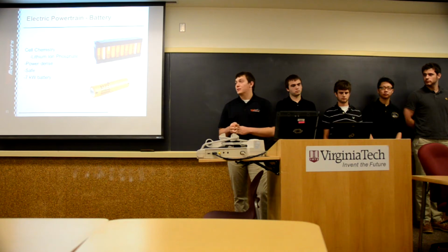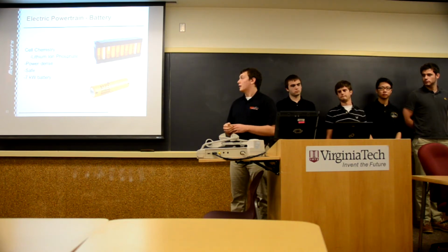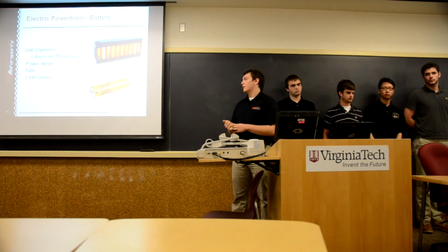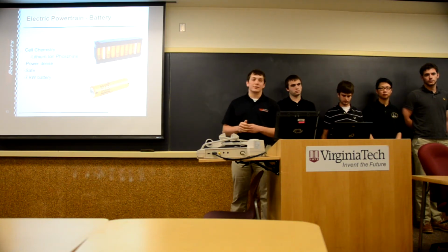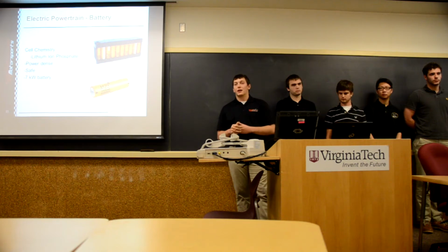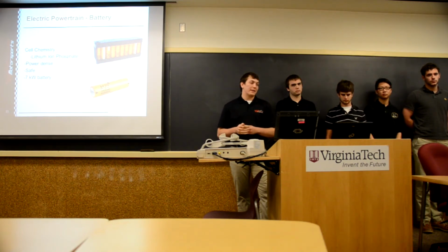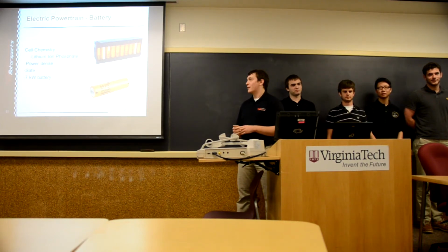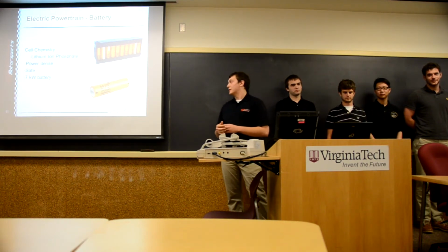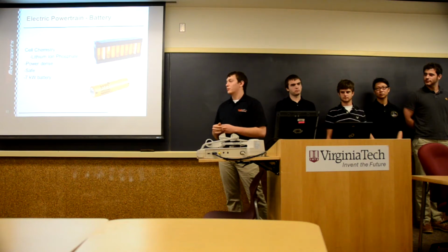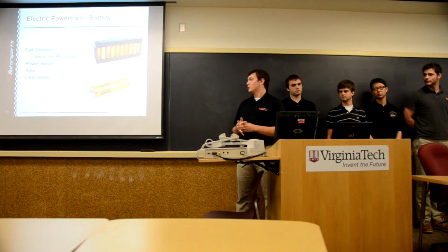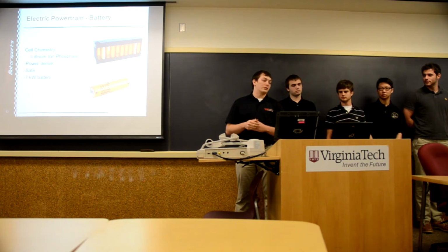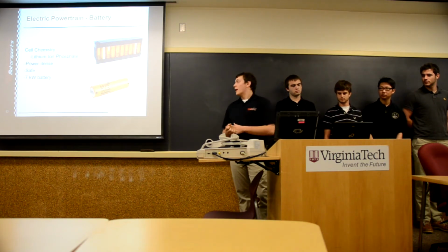A little bit about the batteries. We are going with a lithium-ion nanophosphate battery, and the main reason for this is safety. Some of the lithium-ion metal oxide batteries have failure modes of igniting or combusting, and this would be very bad. So we're going with these. These batteries are rigorously tested, and they're extremely safe. You can drill through it, you can smash it, you can draw too much out of it, you can overcharge it, and you might break the battery, but it's not going to act in any harmful way.